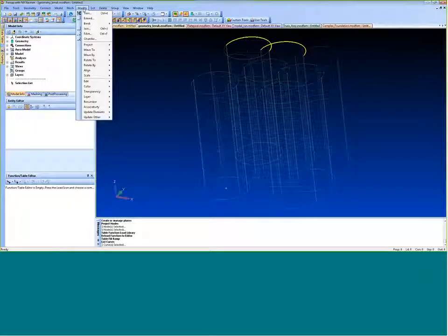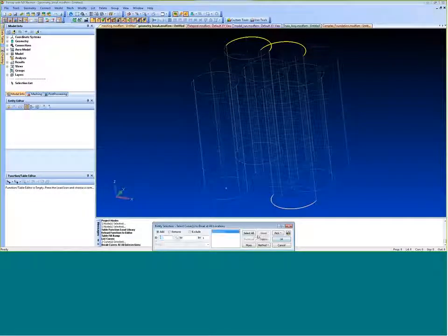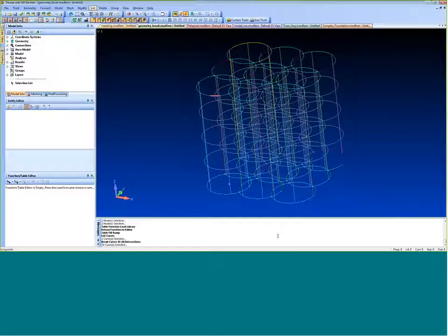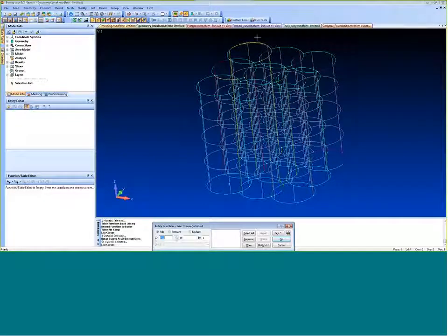Now there is a new option under Modify, Break, at all intersections. You can either select all, or you can highlight whichever ones you want. It opens up this GUI window, where you say which curves you want to intersect, and it's just going to do it automatically with that one click of the button. Now if we go back to look at these curves, I click those same two, and they stop right at that intersection point.